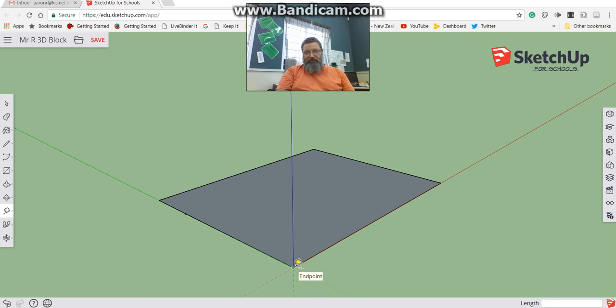I'm going to come down to this point, and I'm going to do the same down this end. Now I don't actually need this guide point, but it'll help me check my work. So I'm going to go along this line, I'm going to type the number 10, press enter, and I've created another guide point there. That's 10 millimeters in, and that one there is 10 millimeters in from this side.